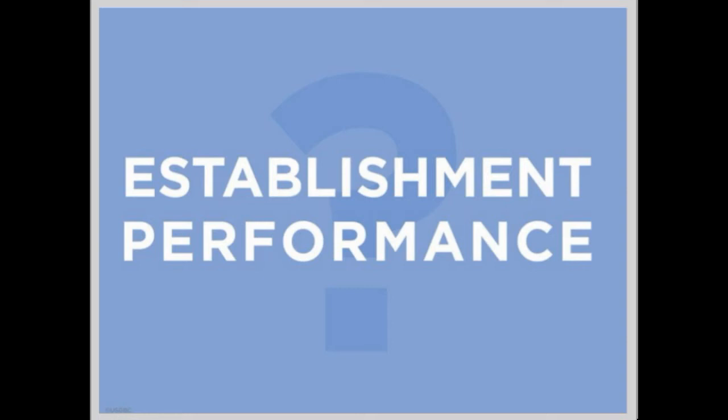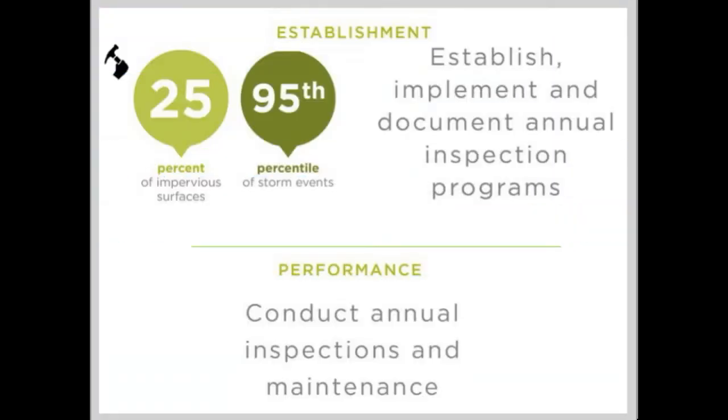There are both establishment and performance-based requirements for the credit Rainwater Management. The establishment requirements include using low-impact development, or LID, practices to capture and treat water from 25% of the impervious surfaces for the 95th percentile storm event.